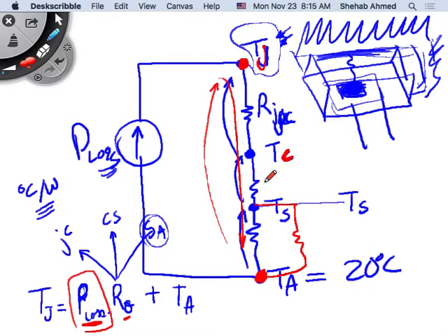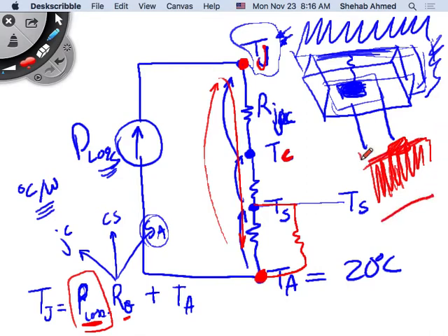And now, okay, the heatsink itself. This heatsink can be a sheet that's this big, or a sheet that's this big, or a finned heatsink, for example, that you've worked very hard to increase the surface area, right? Heat dissipates better for a larger surface area. That's why these fins are there on heatsinks that you may see, right? It's all of this surface area between the fins that can help dissipate the heat, right? So if you compare this versus just a sheet of the same size as the top part of the heatsink, this is a much better way to sink the device because of the surface area that you have here, right?